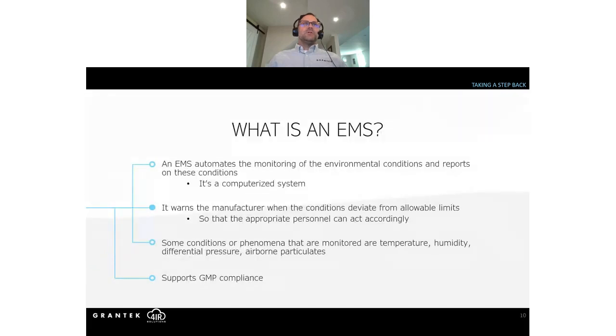To monitor environmental phenomena, you could have someone walking around manually recording the information, reading the values from analog gauges or digital displays. That would be time-consuming and would introduce the potential for human error. EMS systems automate this monitoring function, reading data from sensors that capture the environmental conditions and convert them into signals. These signals are then logged and can be trended, displayed in reports, or used in analytic systems.